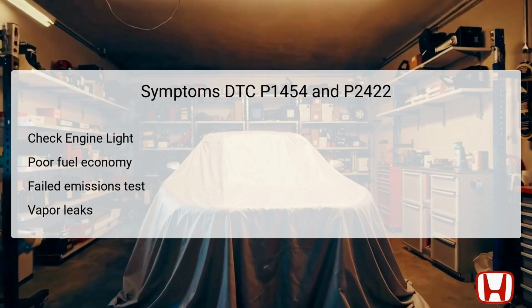Common symptoms associated with DTC P1454 and P2422 include the illumination of the check engine light, signaling that a problem exists within the emissions control system. Another symptom often reported is poor fuel economy due to inefficient combustion driven by incorrect sensor readings. Drivers may also experience performance-related issues that can include rough idling or hesitation during acceleration as a result of disrupted